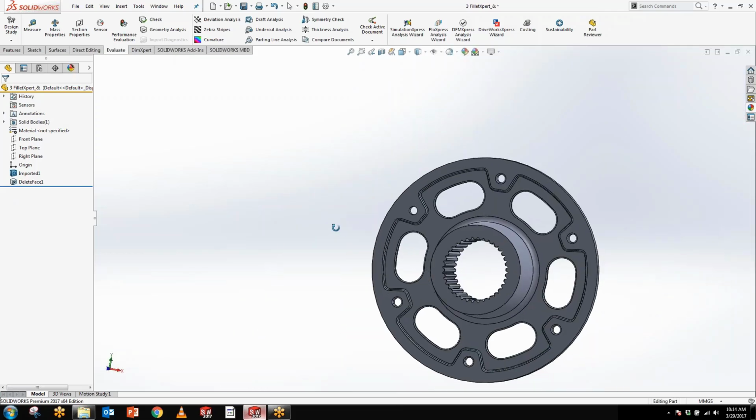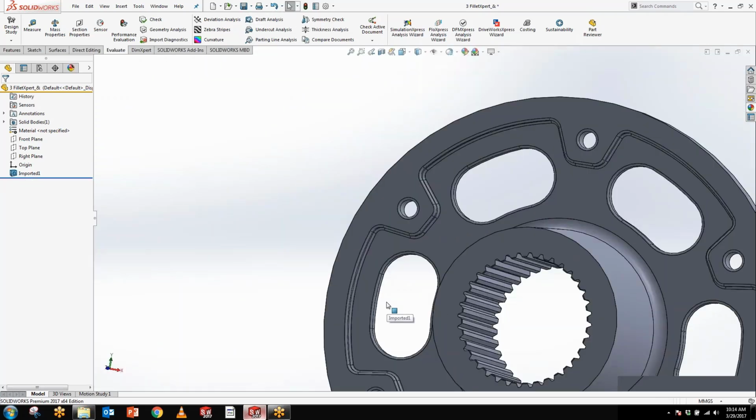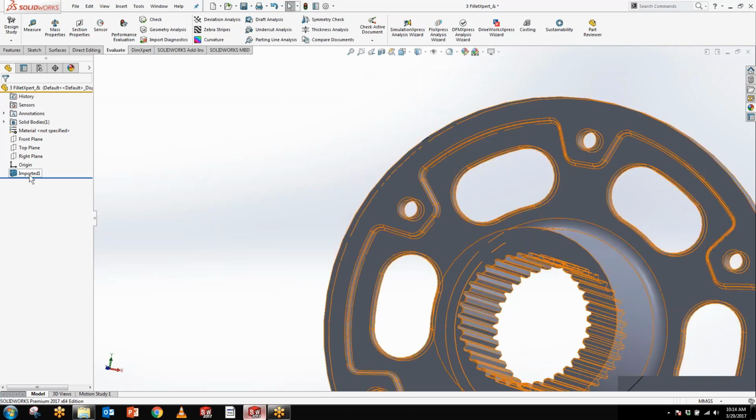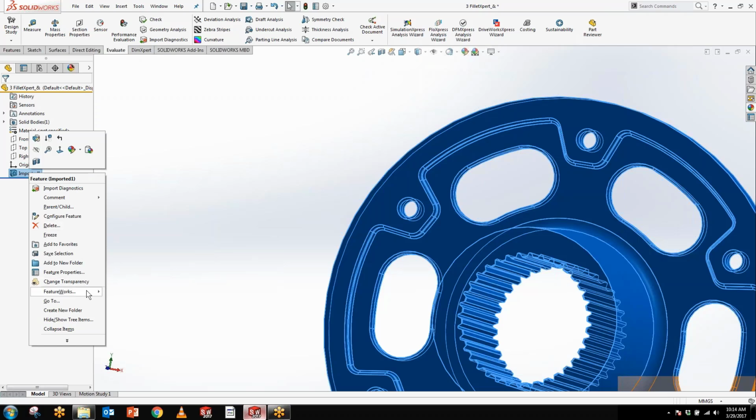So as an approach to simplify my part, guys, I went ahead and deleted one of those fillets. But sometimes when you have a part with multiple features like that, you don't want to be doing these things individually. That's why let me undo this. Let me go back and undo. And from the feature tree, let me right click on my imported part and recognize features. Let me run it from FeatureWorks to recognize all the features in my imported part.